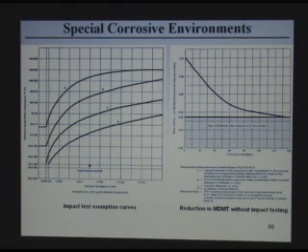So you start with carbon steel, and if you impact test, it becomes like low temperature carbon steel. And if that is still no good, then you have to use low nickel alloy steels. And in the worst case, you go to stainless steel. So this is a sequence of material selection due to a low temperature environment.